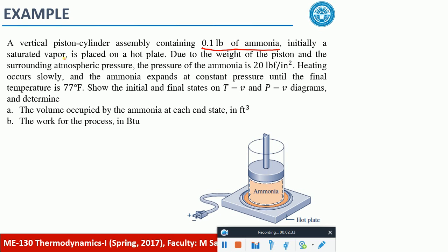Now this is very important. Whenever you are reading that statement, you should be very sure about the identification of the regions on that PVT surface. You should keep those surfaces in your mind, have every piece of information about the projections and the PVT surface, and then relate all the statements to that. For example, this is initially a saturated vapor. Can you imagine where that point would be lying on that PVT surface?